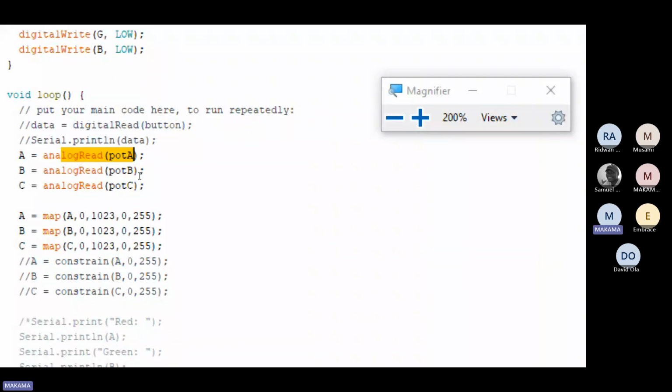If you divide it by 2, it is 2.5 voltage, it will give you the number that you divide by 2, which is around 512 or something. So that's it. That is how you do the analog read. So once you do that analog read, I believe we all know how the potentiometer works, right? You can adjust voltage from 0 to 5 volt. So I will be adjusting my potentiometer, collecting that value and storing it in the potentiometer variable. What shall I do next?